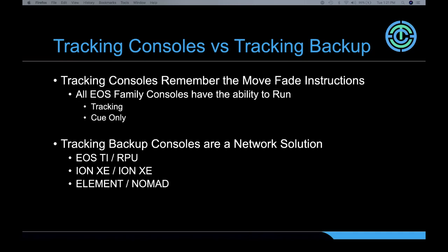And if anybody does have an ETC console and you're questioning what output count your console actually is at, you can simply get to the home live screen, hit the displays button if you choose. There's an About button from the general settings page there, a dedicated button on most consoles. Hit About, and it's going to tell you your version, as well as your output counts and channel counts in the CIA, the central information area in the bottom right corner.